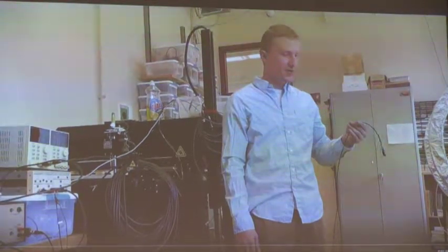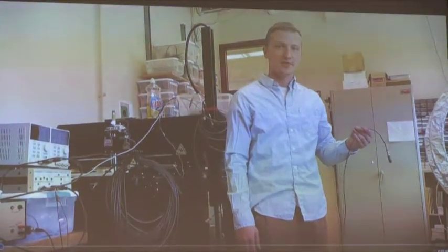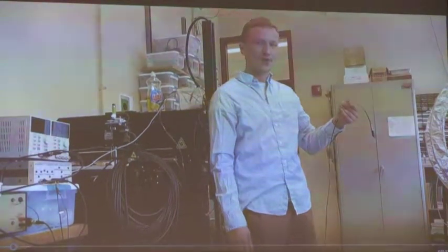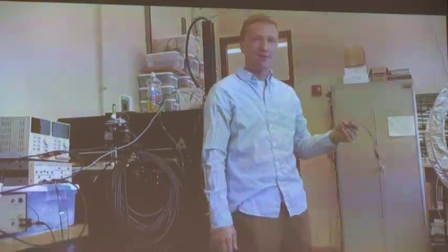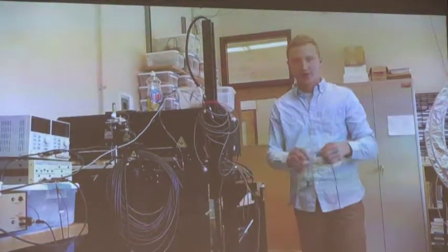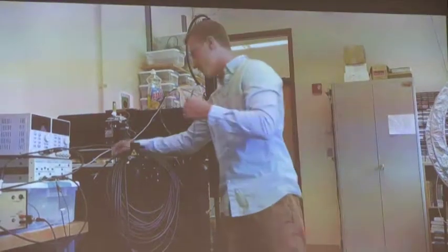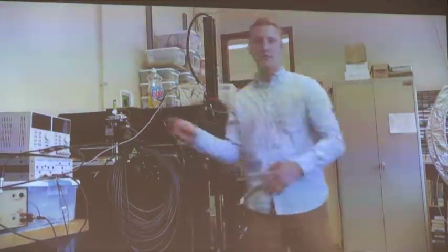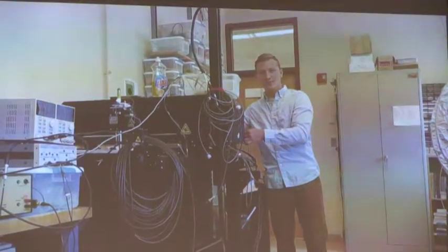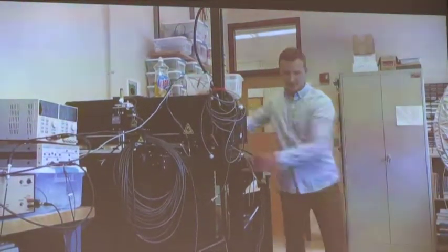All right, everyone. My name is Jim Short, at the CIE building, demonstrating the transducer calibration by hand. Here we've got a BT1201 transducer, which is produced by BTech. On the right side here, we've got an input wire, which will do that calibration. I'm going to place the transducer on the side of the tank, which will receive the signal. About a meter away, we've got another BT1201 transducer, which will transmit the signal.